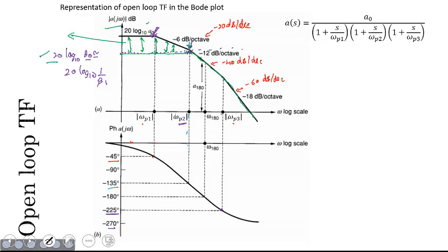What we know is the loop gain, or the phase value, could be extracted as something like A(s) times β, and what we know is this β doesn't introduce any kind of phase shift, right? So anything that we read for A(s) would be the same as that of A times that of β, right? So both these phase values would be the same.